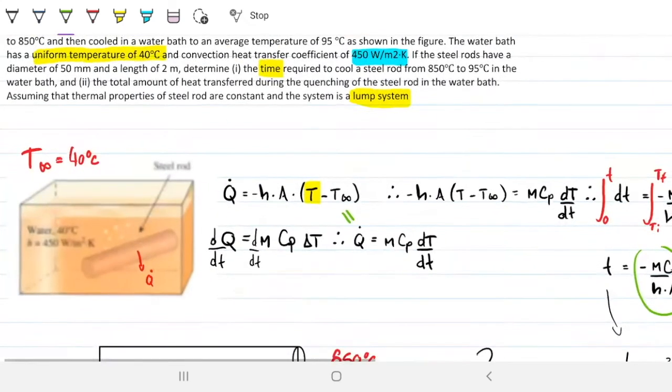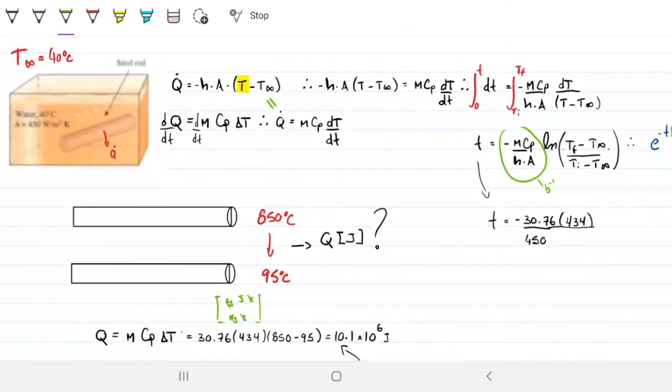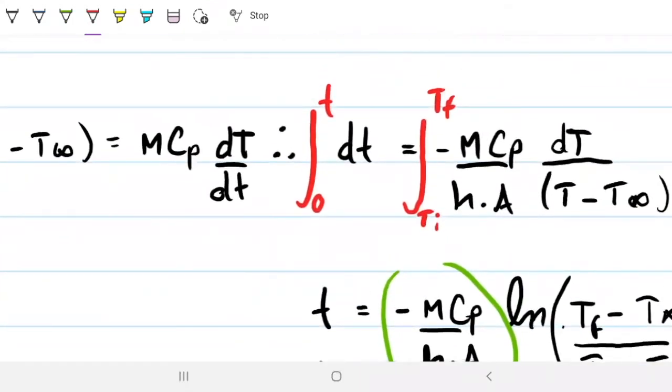Yeah, okay, thank you. Did you put boundary conditions, the TF and TI? The big T's are temperatures, right? That's correct. The big T's are the temperatures. And here it doesn't have to be TF. This can be any temperature you want, right? So you can do it halfway through the quench. You can say, oh, well, how much time is it going to take until it reaches 700, and you can find the time there. So it's up to you.